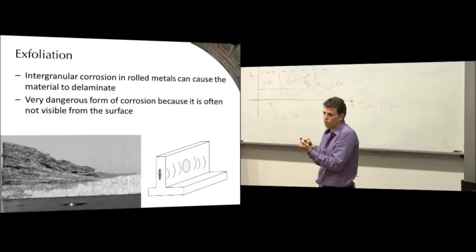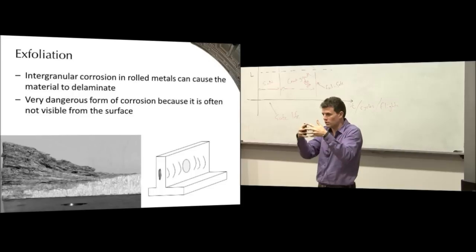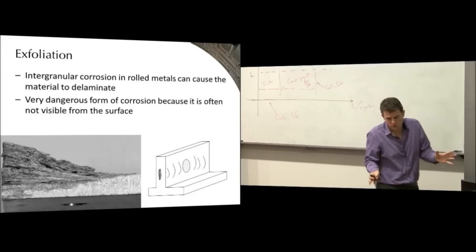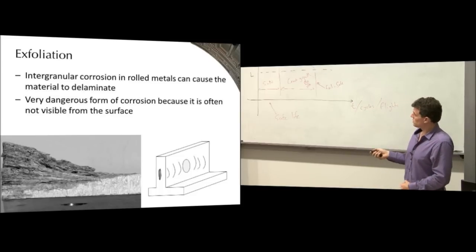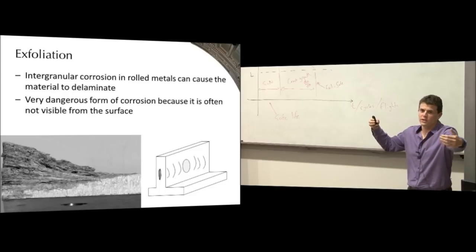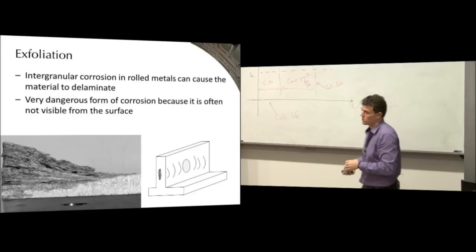Now, if you pick up your exercise book that's in front of you and load it in tension, you'll get most of the strength of the book. If you try and squish it, the pages will just separate. That's what's called brooming failure. There's no compressive strength in a stack of paper, and that's what happens when you get intergranular corrosion. It loses all structural integrity, and sometimes you can get off the ground because something's loaded in tension, and then you'll hit a gust and it'll be loaded in compression and your part will fail. So it's a dangerous type of corrosion that we need to deal with.